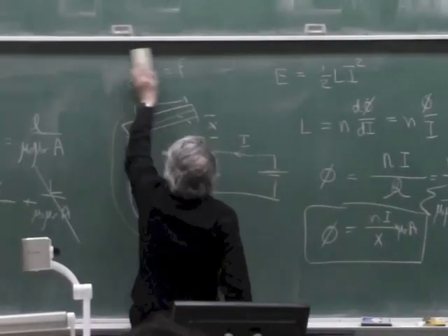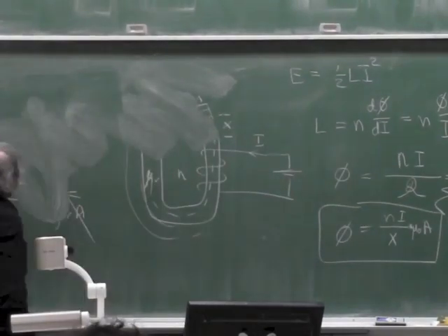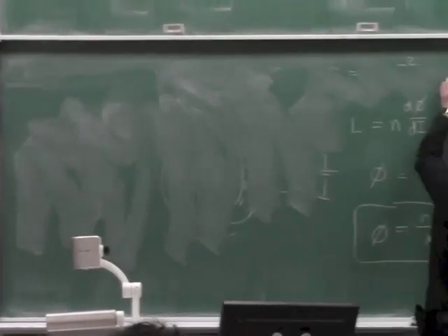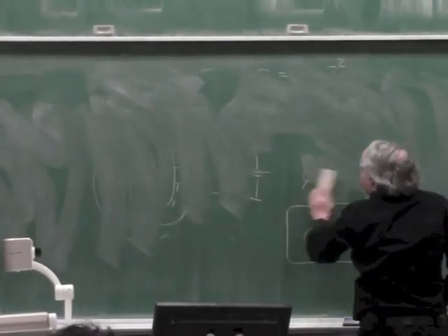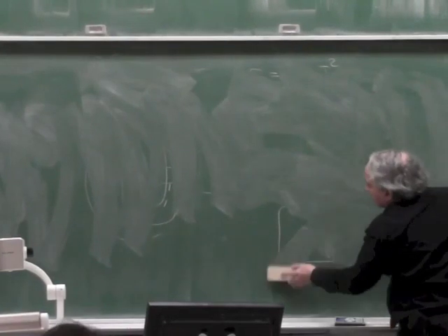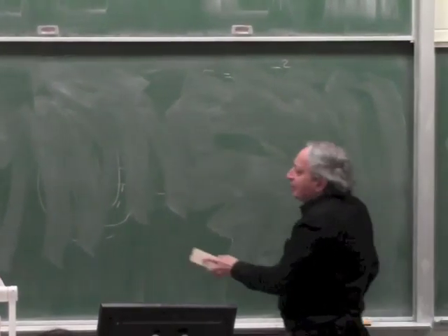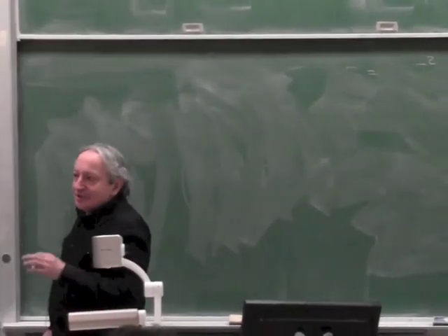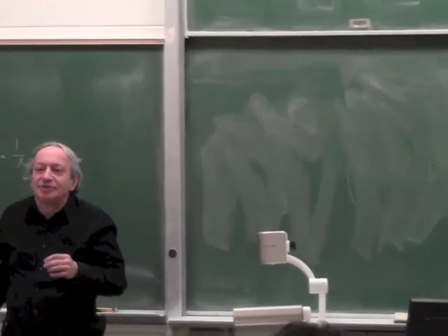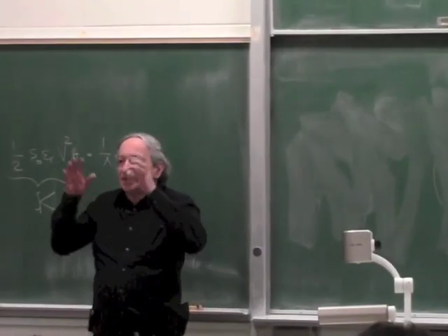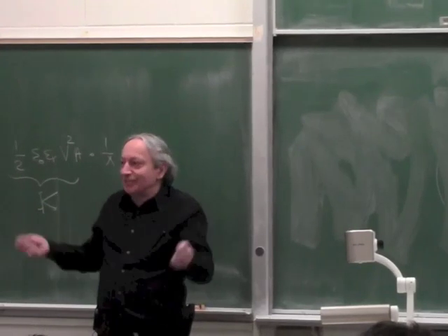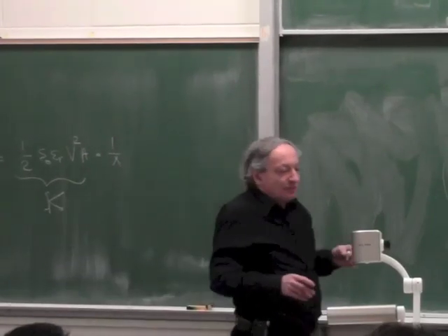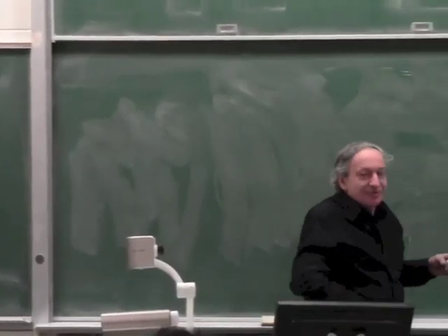By the way, this method of getting the force by the derivation of energy is also used in mechanical engineering. In mechanical engineering, it's sometimes referred to as a virtual work principle, which you may or may not have heard of. It's a very, very useful principle to derive, say, stresses in a structure or hoop stress in a boiler, things like this. It's a very useful technique in mechanical engineering, this virtual work principle. You can look it up if you don't know what it is.